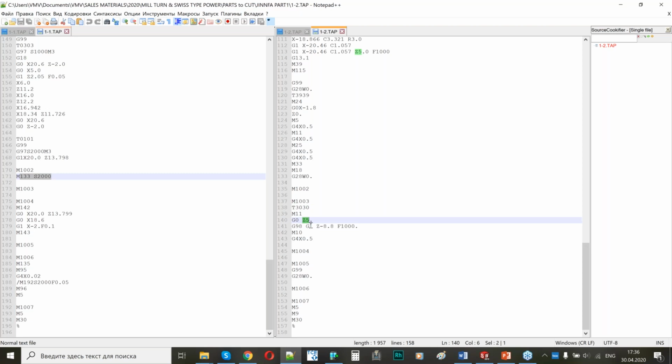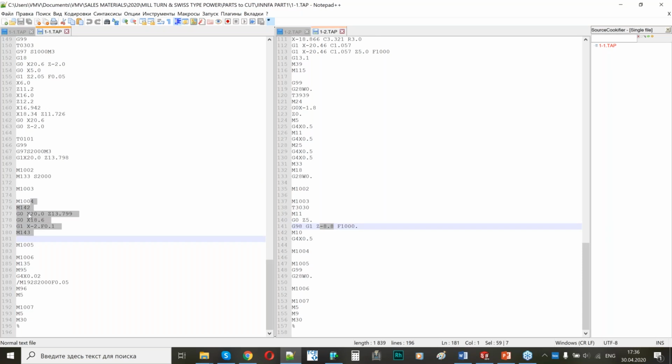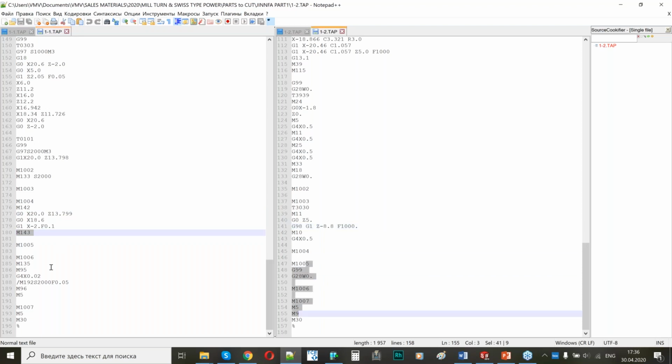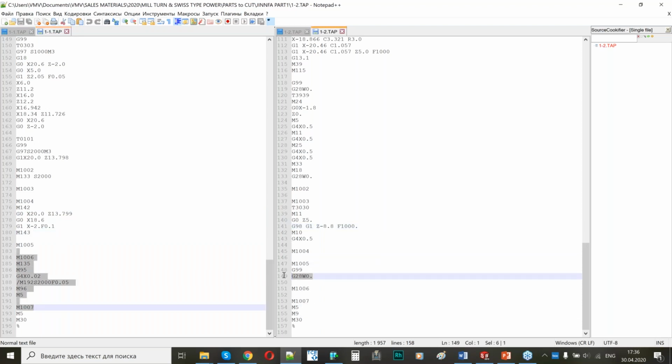This is the special code offset on the CNC to position the back spindle, because as you can see, it positions according to the part coordinate system, not machine coordinates. So it's a safety position. This is the clamping position. It is calculated from the machine setup. Then I will have the cutoff process with the Z synchronization special commands for this machine. And then I will have some codes to put my back spindle to its home position, and some commands to prepare the bar for the next step.